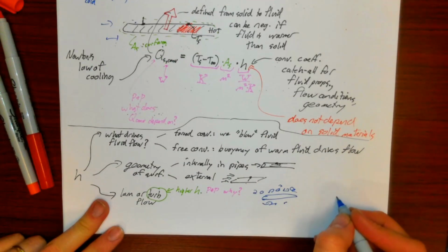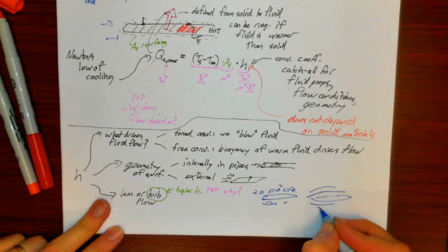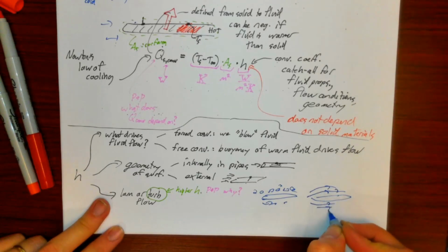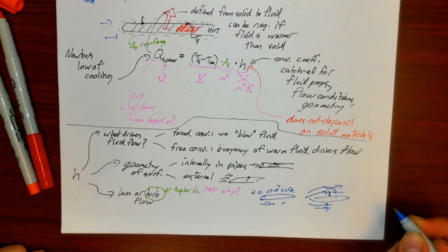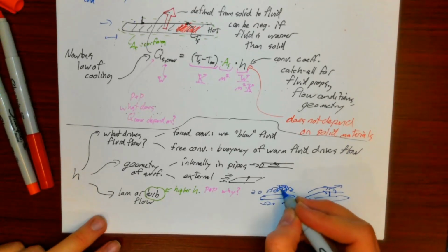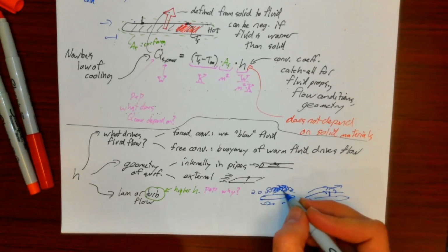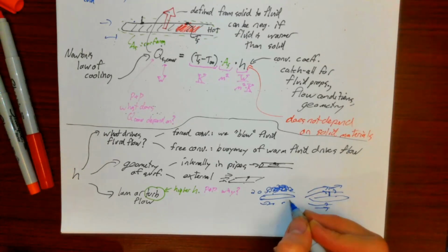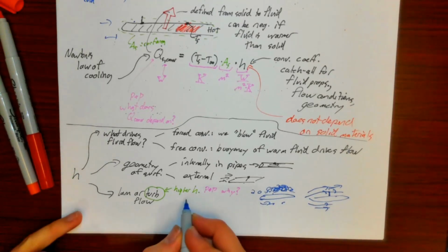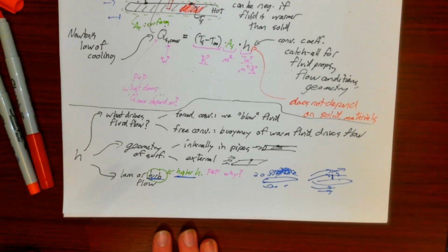And in laminar flow, all of those streamlines just keep to themselves, and it requires that heat to cross streamlines to get carried away. Whereas turbulent flows are mixing everything up, swirling, getting that cold fluid right in contact with the surface and then sweeping that now hot fluid away, far away from the surface, to replenish with more cold fluid. So turbulent flows typically result in higher heat transfer coefficients, higher convection coefficients.